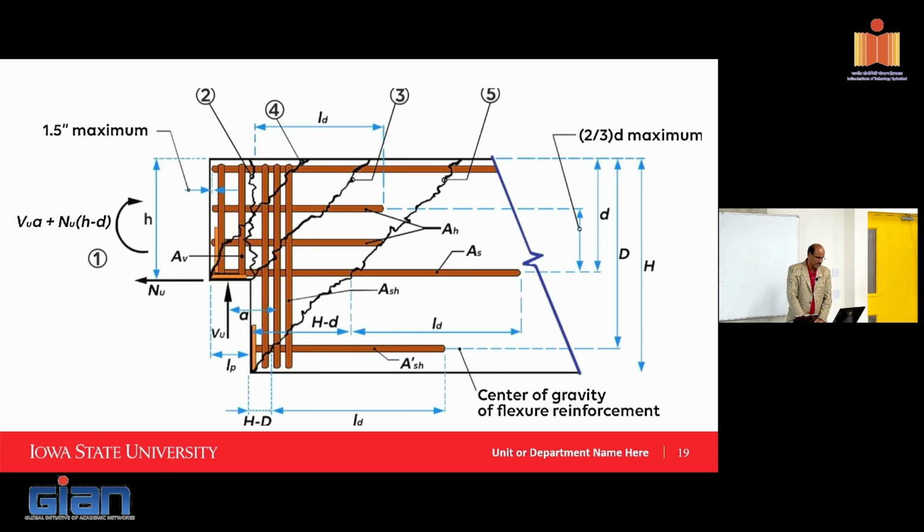So this is especially when you have a section, so you're looking at the end of, say, a double T, for example. So one of the T's comes here. Here's a pad, and an inverted T on one side or an L beam will be supporting it. Now this section becomes critical in terms of this area getting sheared off.